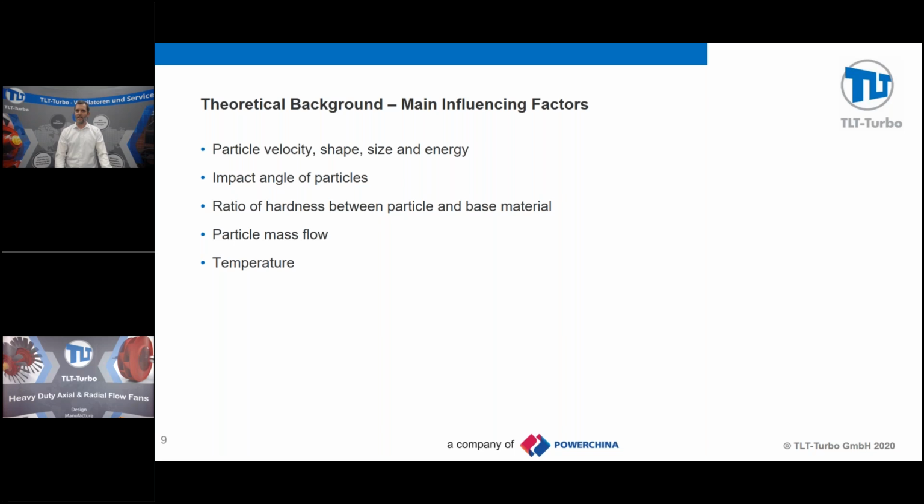But it's not only that, it's also the impact angle, so if they are hitting straight or if they're only touching a little bit. It's also the hardness of your particles and the hardness of your base material or your wear protection. And also it's particle mass flow. Every particle transports energy, so the higher your mass flow is, the higher your total energy is.